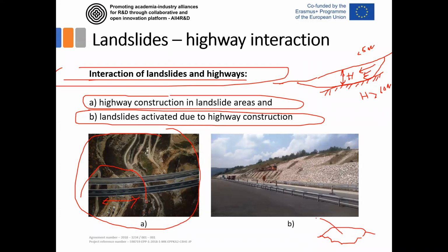And after the excavation of this, an instability occurred here, and all this part of the wall actually slid in this area. So this is a typical landslide that occurred after the highway construction. Of course, before the highway construction, no chance of any soil sliding was possible because the hill looked like this and then went here. So from both sides, it's excavation like this.